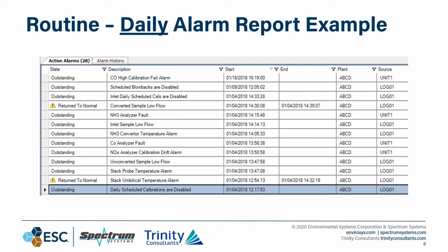And so I encourage folks to really review how the control room is set up. Can you see the CEMS alarms? Do you have nuisance alarms from the CEMS commingled in operational alarms that could keep you in a desensitized situation to where you might miss something and actually cause an exceedance or an emissions problem? And that is a valid point. You can have so many alarms on the screen that it can just create a form of blindness to a problem that could be right in front of your face.